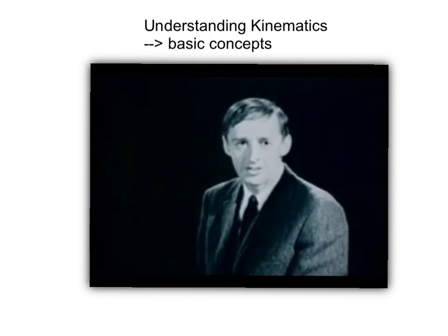It's an advantage of the laboratory coordinates that there's often a frame of reference in which the Eulerian field is steady. We can use an Eulerian frame of reference, where we observe a fixed flow field rather than following individual moving fluid elements. In this Eulerian method, we study the properties of the flow pattern in terms of spatial position and time. In a few cases, it's more useful to follow a specific fluid mass through a flow field using a Lagrangian reference frame attached to the mass.